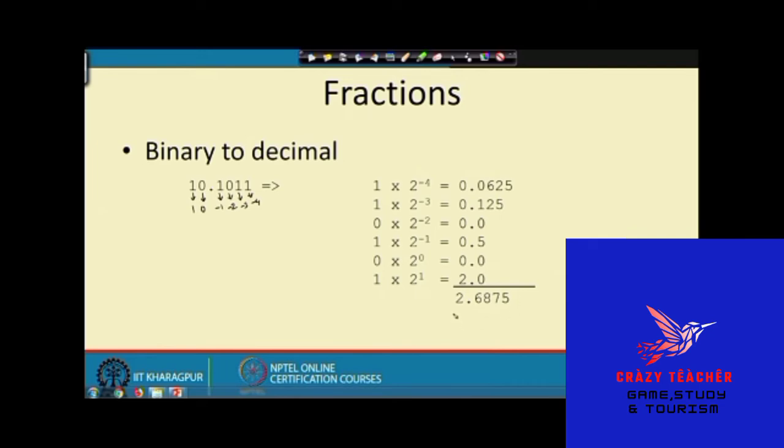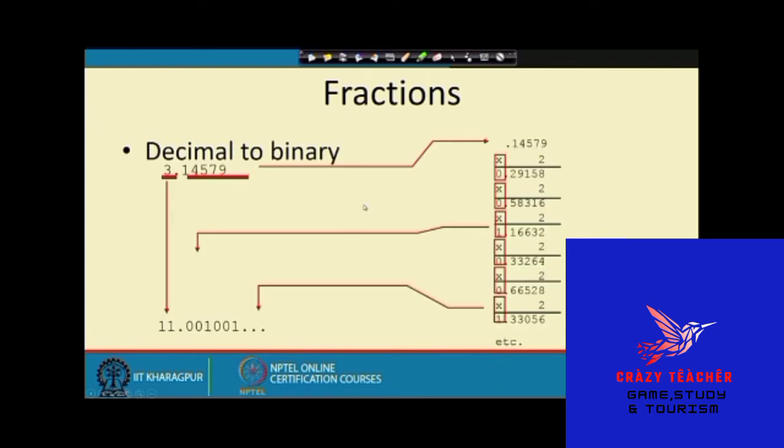If we are doing multi-bit multiplication, we follow similar rules to the decimal one. First this is multiplied by 1. If it is a 1, you basically get back the other number, so this is 1110. Then there is a shift for the second bit multiplication, so you get 1110. Then another shift, but this is multiplying by 0, so all are zeros, and then another shift and multiplying by 1, so you get 1110. Ultimately you get this as the result. This way the rules of multiplication and addition remain the same.